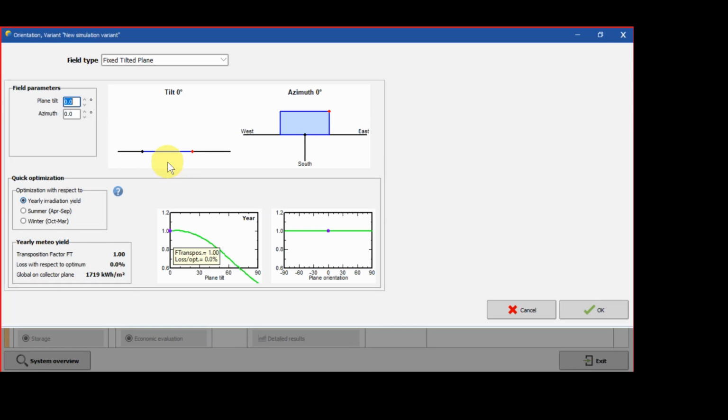Furthermore, if there are raindrops, the rain will accumulate on top of the modules, right? So we want to avoid that. So typically in Malaysia, the angle is around 10, 15 to 20 degrees. Actually, we can play around with the values here. Okay, let's say now I put 15 degrees, yeah? I press enter.